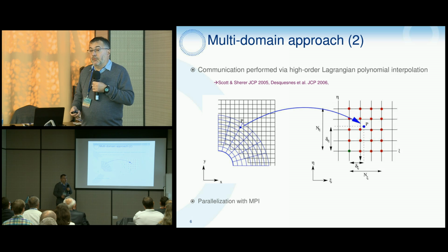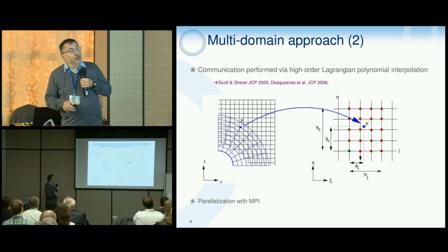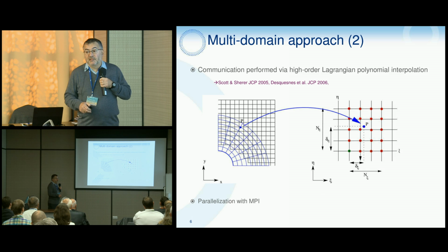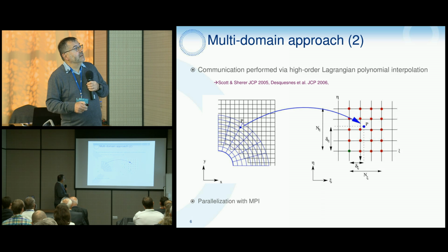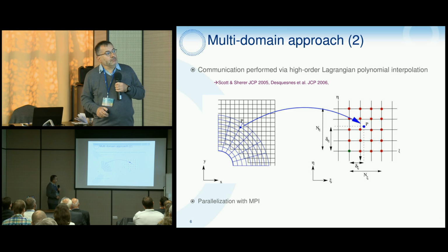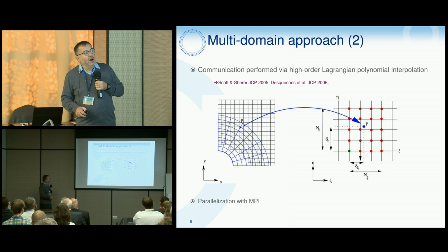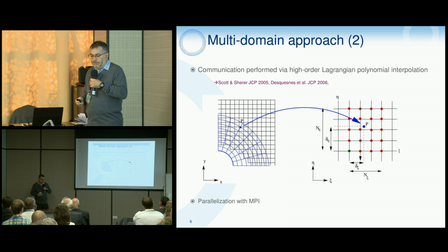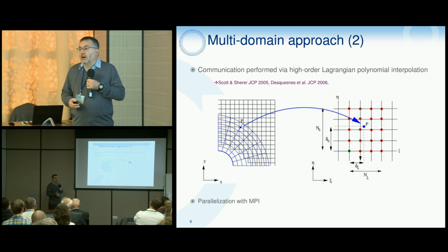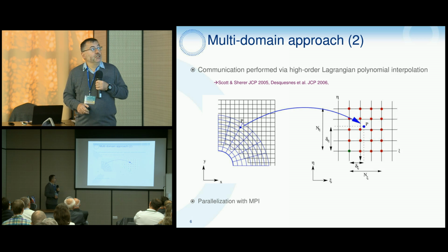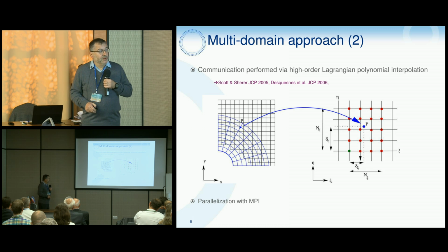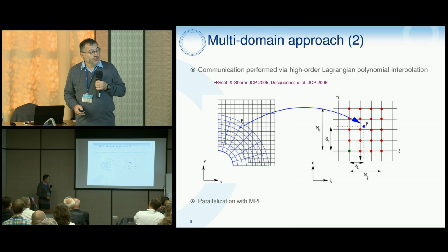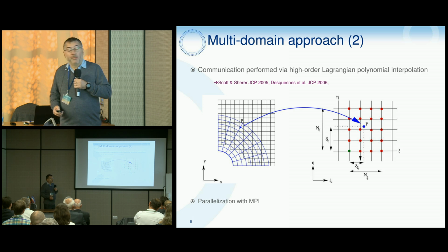One key point in this approach is the communication between the grids through interpolation points. The interpolation process is made on a transformed grid. It's quite well described in the Henshaw and Schwendeman paper, especially, for example, the definition of what is called the delta, the offset. It's a key point in order to have accurate computations of the interpolations. And of course, we use MPI in order to parallelize the code and to be able to have HPC capabilities.